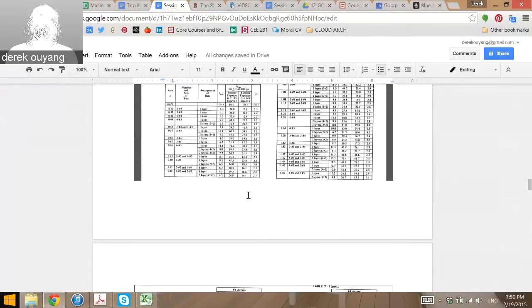And basically, you can then create a spreadsheet where you're just iterating over every possible combination of B, D, and H. And those are all possible designs, right? You can make a million of them for any given problem, but some of them are going to make no sense. You know, some beams are going to look like this, some beams are going to look like this. And often what you're constrained by is this.